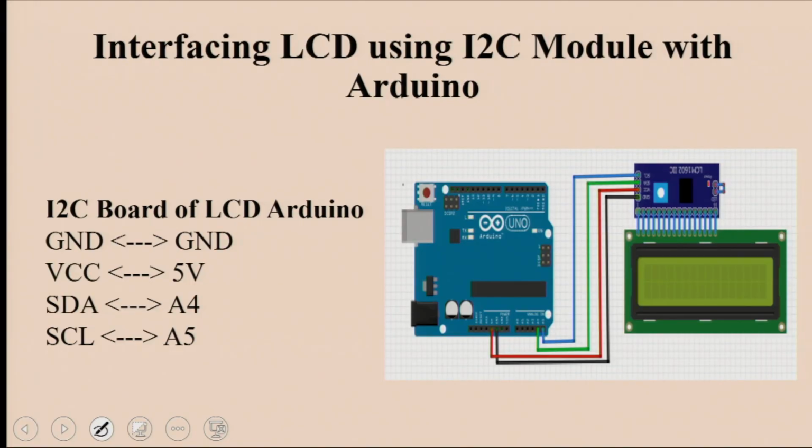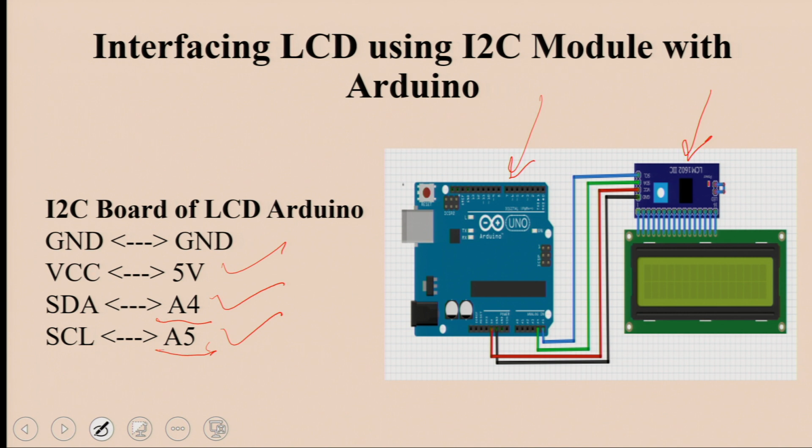But along with this, you might have seen the description that even these two pins from your analog port can be utilized for making your serial data line and serial clock line connections. So, currently in this particular experiment, I am going to use these analog pins as my serial data line and serial clock line. So, now you have understood the simple connection interface on your screen.